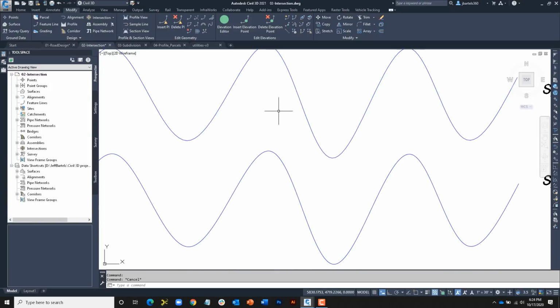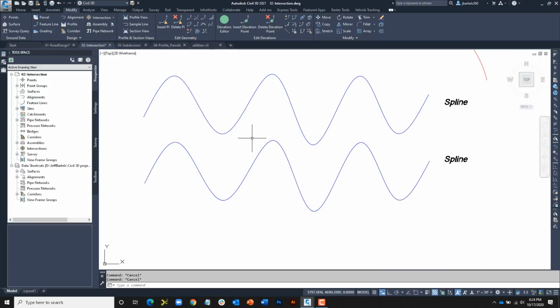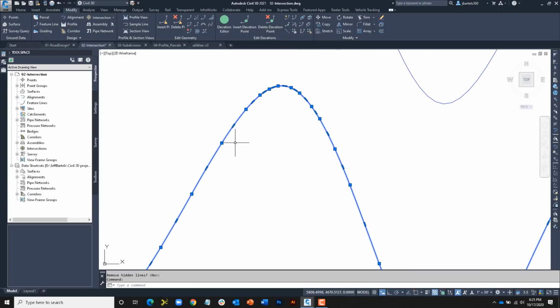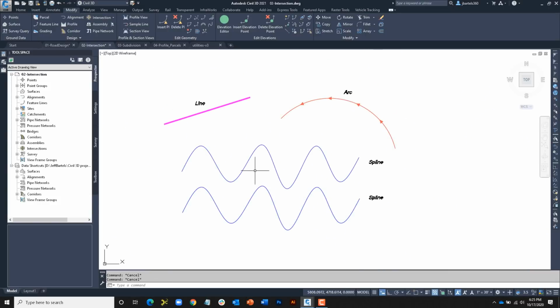Let's back up. Sometimes, if you're working with planar splines, a better way to convert them is by using the Flatten command. Flatten is an AutoCAD tool that's used to convert 3D geometry to 2D. I'll type Flatten and I'll press Enter. I will then select this spline and press Enter. Note that I'm asked to remove hidden lines. In the event this object was in 3D and I had entities that were coming straight towards me, they would be hidden from my view. I don't have any of that, so I'm just going to hit Enter and accept the default here. And if I select the resulting polyline, you can see that it's got fewer grips, it matches the geometry better, and the entities are actually curves. Let me press Escape, and then we'll back up.